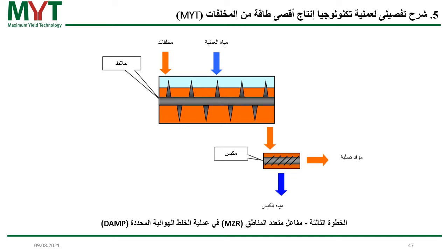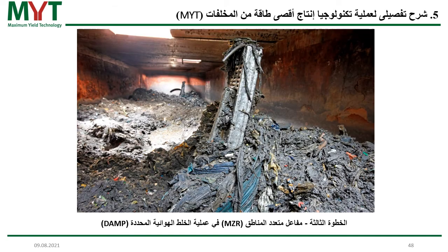It is extremely important to make this clear with this slide. We create from the waste 2 phases. We create a liquid phase, which goes to the biogas production, and we create the solid material, which is the press material, which goes into the biological drying process. I show you a picture of how it looks inside the mixer. On the next slide, what you can also see is that there is no biogas production in this step.